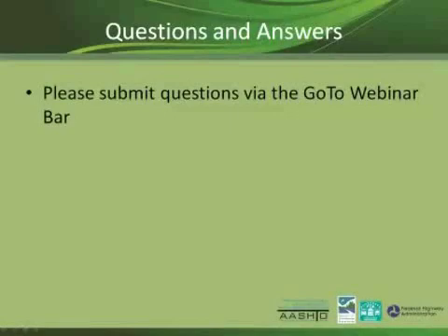Okay, and then Mike, this is back to you. There's a question about essentially paint striping, and I guess the other was the little bump-ups. I forget what they're called, but how does the permeable pavement affect your ability to both paint and keep the paint on? I don't really talk to the tech side about that, but all of those roadways are striped. They're all highway 3-lane or so kind of thing, and just from my experience driving on the one near here that's been down 6 years, I haven't seen any issue at all. And TxDOT's using it on Interstate 35, and some of the sites that Caltrans monitored were on I-5, and Bill Hunt's sites were on an interstate. So it seems to be not an issue, from what I've seen.